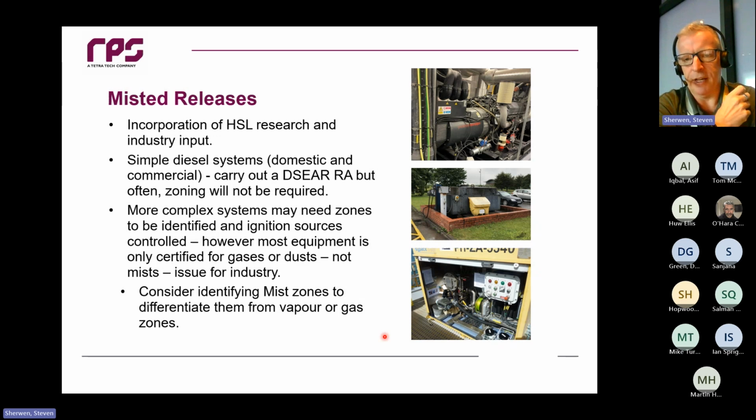Hopefully that helps a lot of people in the industry to say, right, I've got a simple diesel system, I've got a tank that I'm using to fuel forklift trucks. It's all done under gravity or very low pressure. I need to put some safety measures in place, but I don't need to go to the trouble and expense of installing certified equipment, which offers very little benefit.